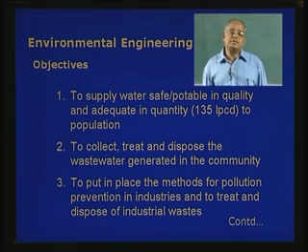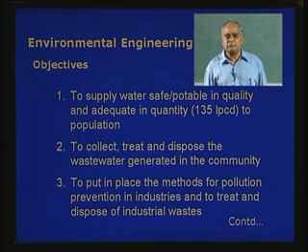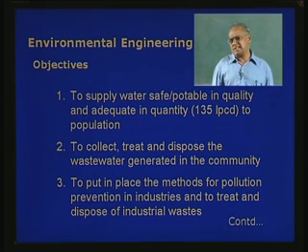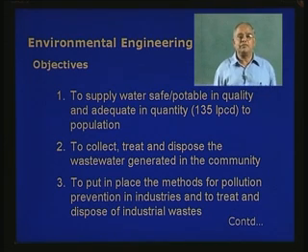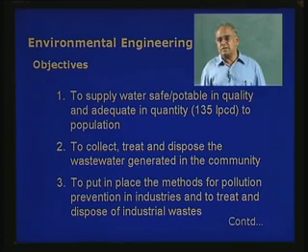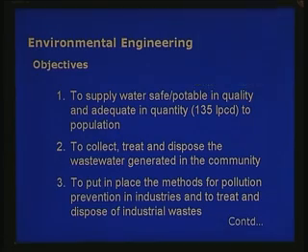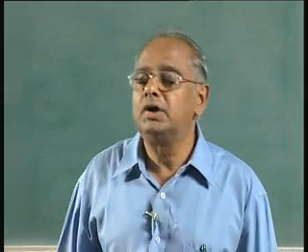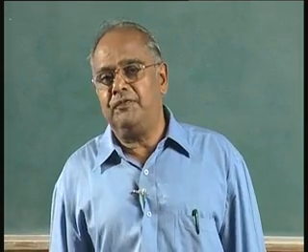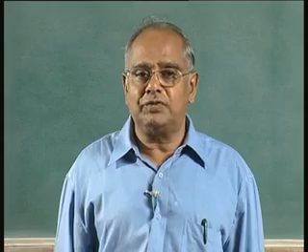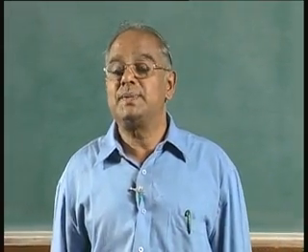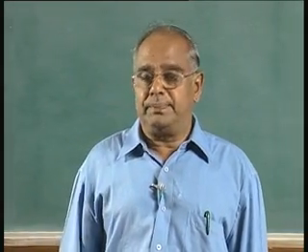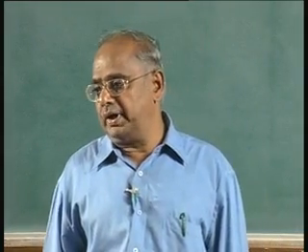Secondly, if I do not supply water adequate in quantity... The Government of India has suggested that we need to supply about 135 liters per capita per day. Per head, 135 liters of water is required. This water is supplied to keep personal hygiene and to meet all water demands. If we do not supply this amount of water, then people would like to get the water from sources which may not be safe. That is a big problem. So, quality and quantity are both important.